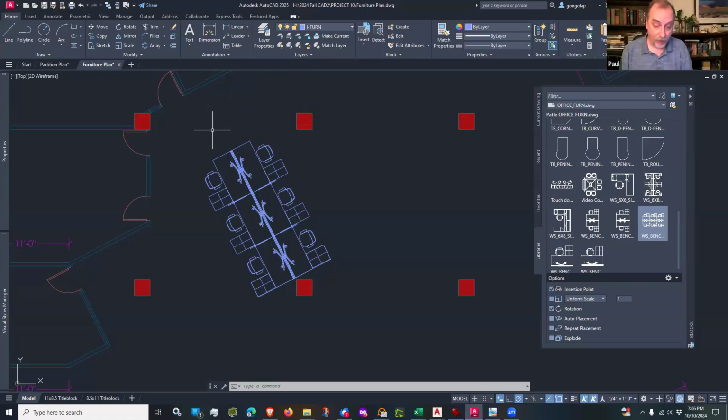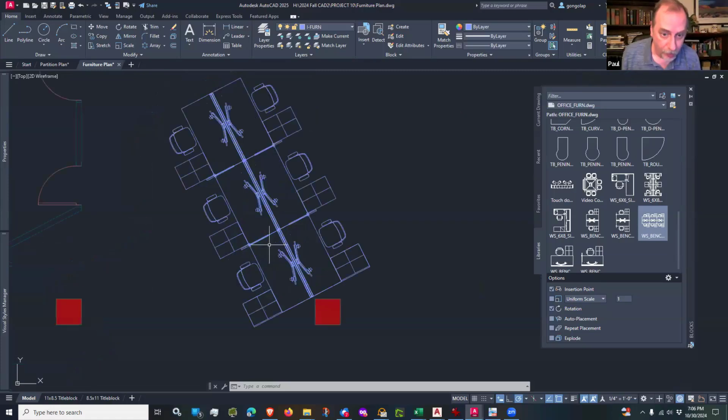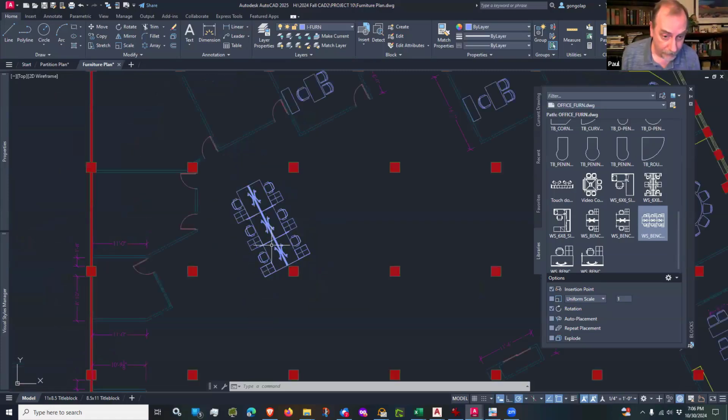So if you don't want the power pole, you do have another choice, and that is to literally core a hole, drill a hole through the floor, all the way through the floor of the building. And then you have to go down to the floor below, to whatever tenant is on the floor below, pop the ceiling tiles, and then run the power up through that hole in the floor. And that's called a floor core or a core, CORE.